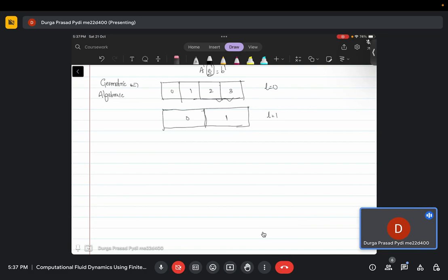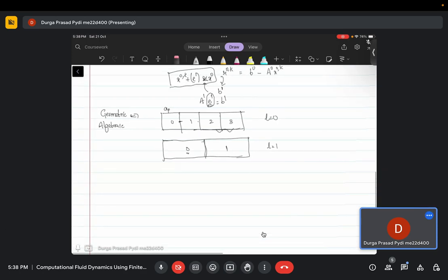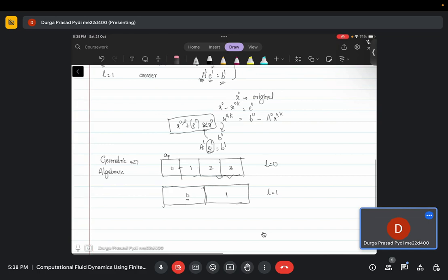So how do you get these values here? Previously you had AP, A and B terms. Now you have to update the values accordingly in these new cells. Like in the new discretization, you need to get the new values of AP, A and B, and then you have to solve for this equation. You get A and B and then you will get E1 from there.